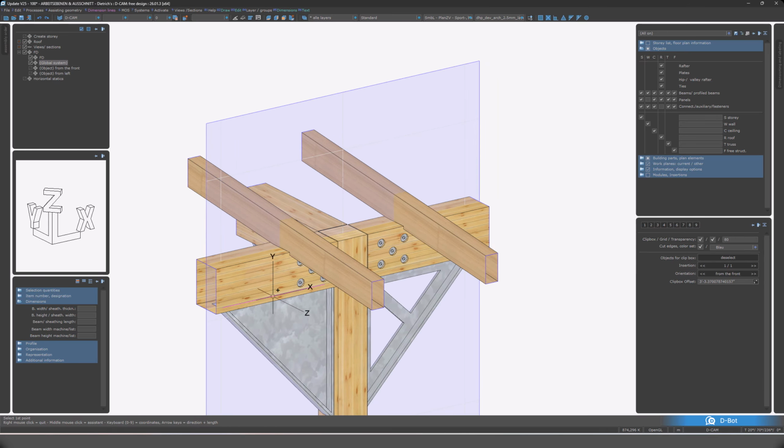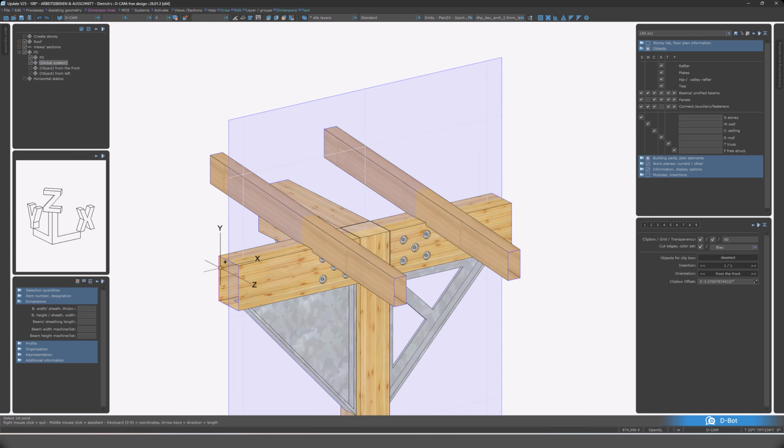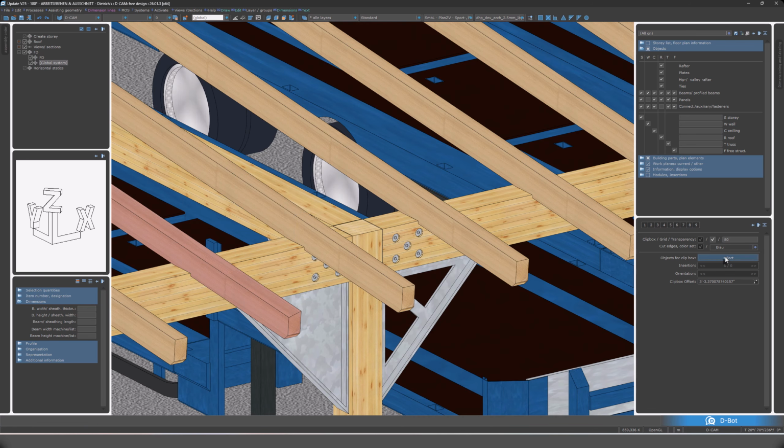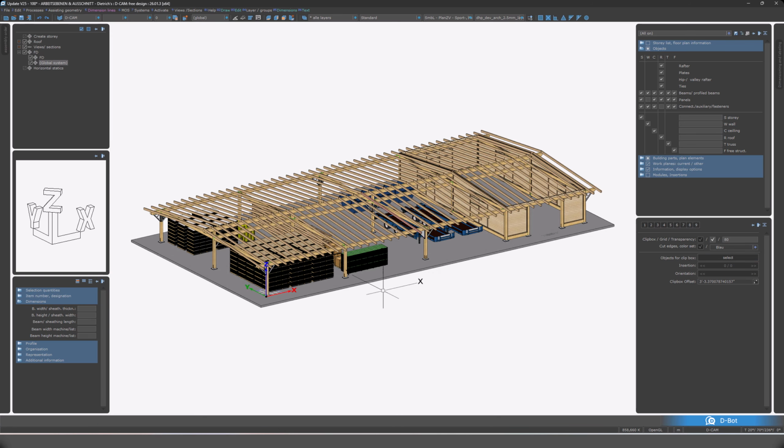With this setting on over here, if you go close to this point, even though this line doesn't actually exist in the global model, you can see that I can actually catch this point, even though that is really not a point that should be existing otherwise if the clipbox wasn't there. And this can be very helpful in certain instances. In the past, before we introduced the cut edges function, you actually couldn't catch this point at all. Let's deselect our column again, and I'm going to fully zoom out.